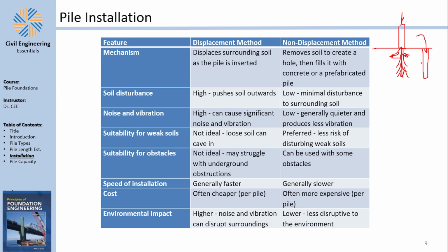There are advantages and disadvantages and differences between those two methods. I mean, one of them, at least, is the bearing capacity and the friction. Because when you disturb soil and when you bore it with an auger, then the clamping force on your pile is not as much as the clamping force or the friction forces if you drive the pile into the soil.